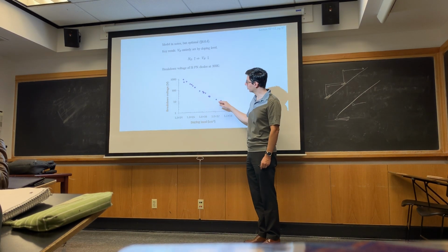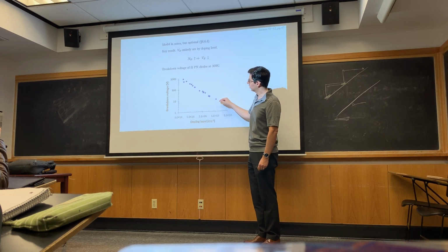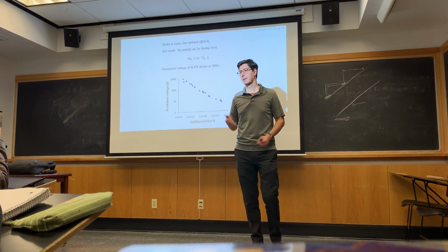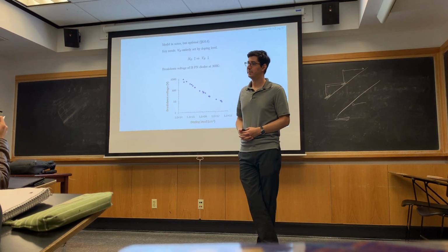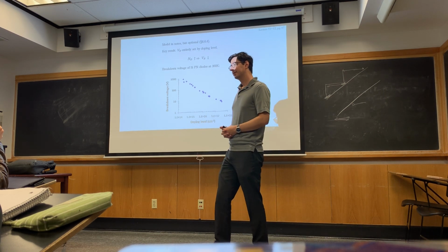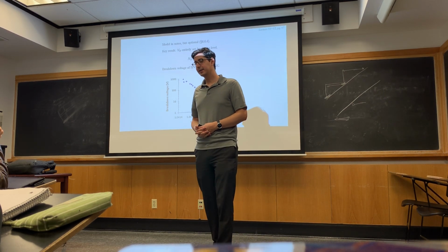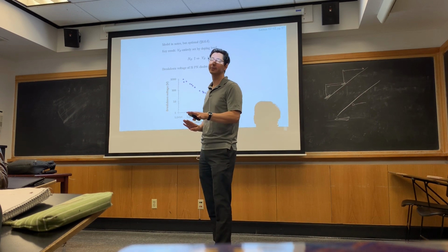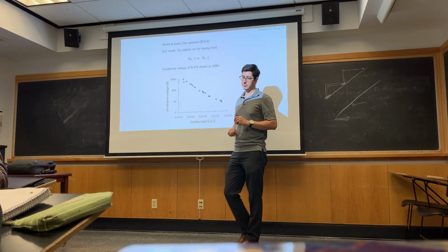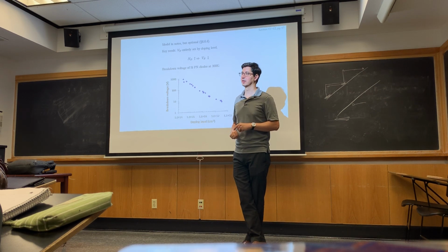Why do you have a lower breakdown voltage at a higher doping? Because in the higher doping, you got more possible snowball to be triggered. Not so. I understand your point, but remember the snowball is actually what is avalanching.